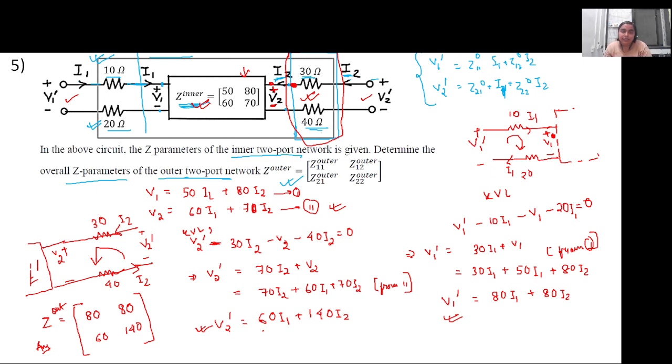But for cascade connection, you need the ABCD parameters in order to straightforwardly calculate the transmission line parameters. But in this case, the Z parameters are given. There is a conversion between Z and A, the relation is there, but since it has not been taught, I have not solved this circuit by cascade connection. Instead, I have simply used circuit analysis to solve I1 and I2.